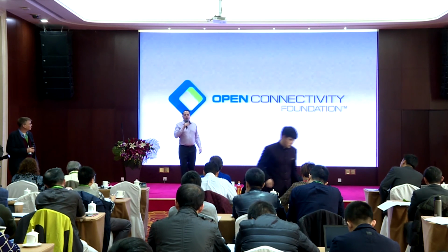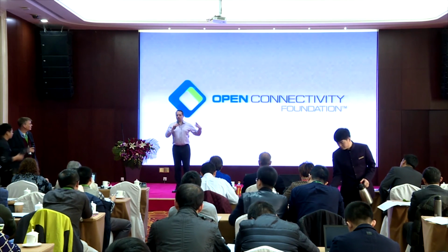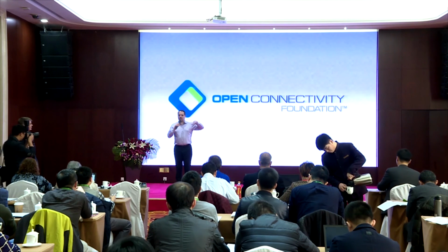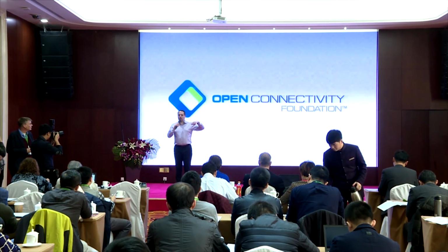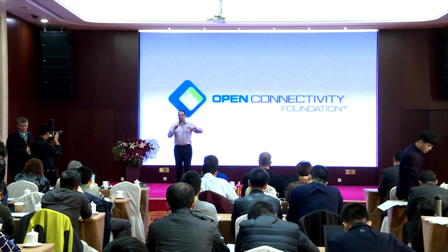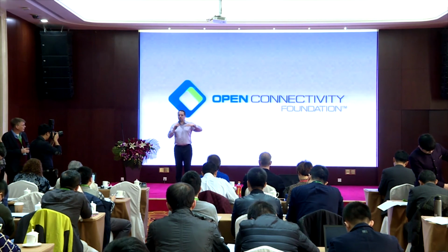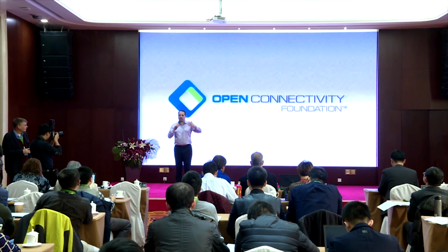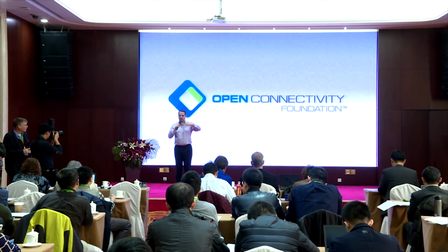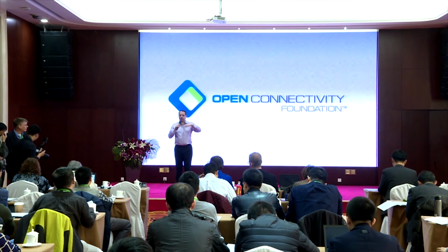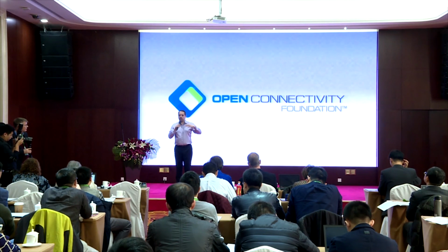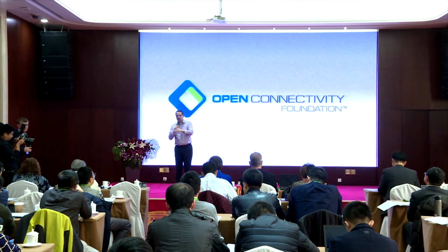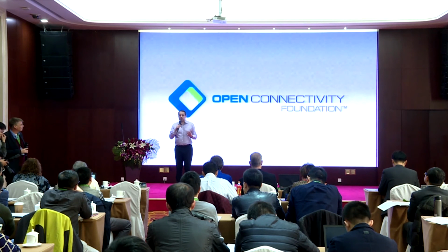Yes. Okay, so there are a couple of well-known resources, oic/res and oic/d, which provide you the basic information of the device. Some of those will be pointers to what are common resources. So it could be a binary switch, it could be a temperature sensor, it could be some things that are well understood in the OCF world, but an individual manufacturer can also define their own resources. Now, it could be a simple binary switch, but it could be doing something that's custom for that manufacturer. Or it could be a completely different resource type.